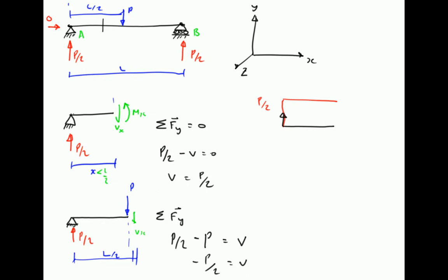Okay, so our P divided by 2 minus P is minus P divided by 2 is our shear force at that point. So we can then say that at the midspan of this, where the beam, this point is L divided by 2, we find that the shear force suddenly changes with the application of that P load to go to minus P divided by 2, and indeed as we carry on at any point within this part of the beam here, that will continue as being P divided by 2 minus P, which gives us a shear force of minus P divided by 2 right the way along until we get to this point here where the shear force is P divided by 2 minus P plus P divided by 2, so it comes back up to 0 at the support B.